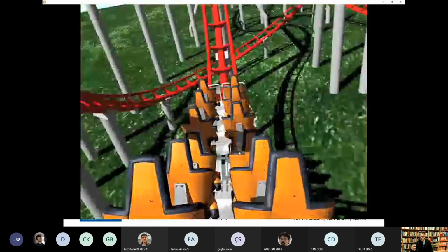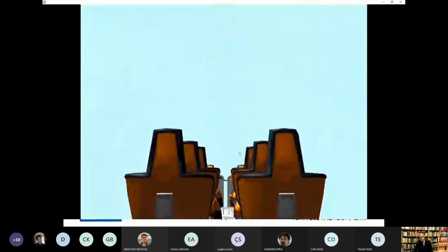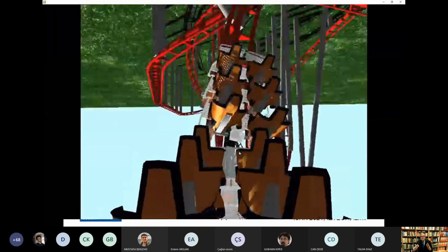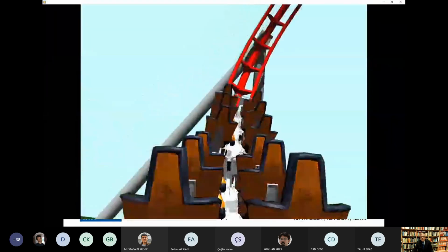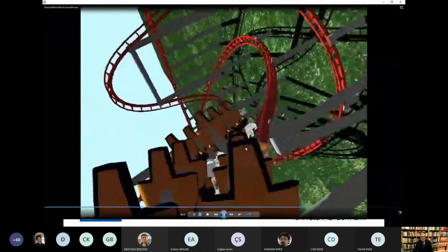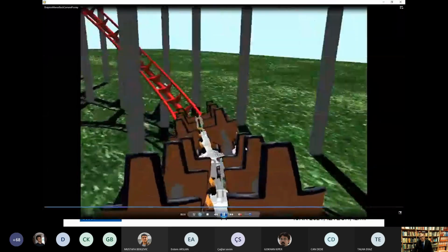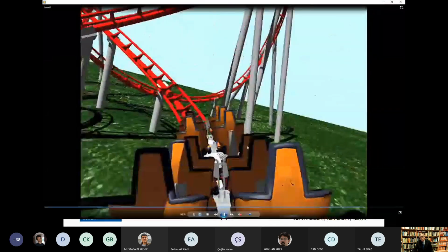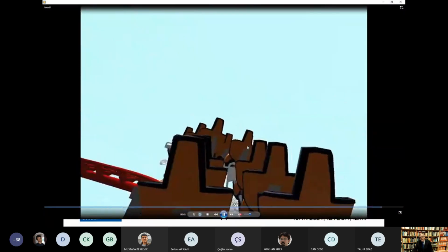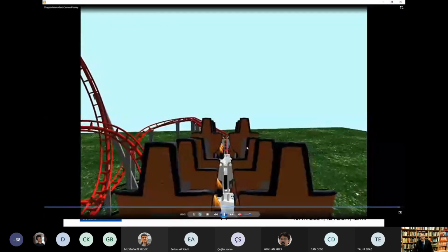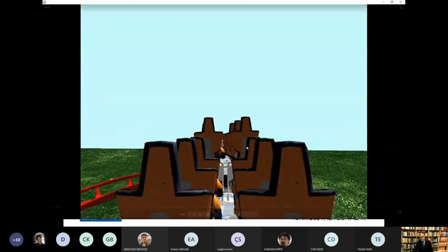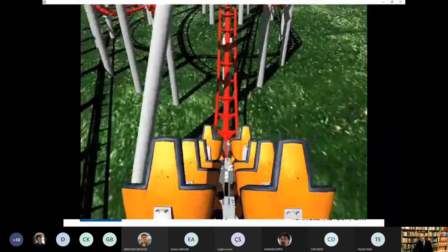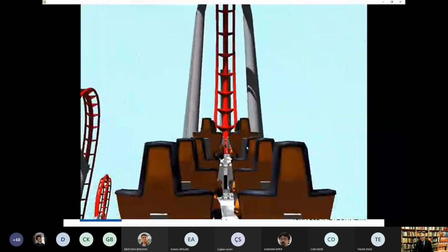the fun is there, but you don't violate acceleration limits, which are linear, but they are a combination of linear limit surfaces. And then all this is modeled by splines of fifth order, because we also have to have continuous rotations, and then the splines are optimized to the control points so that at no position these limits are violated.